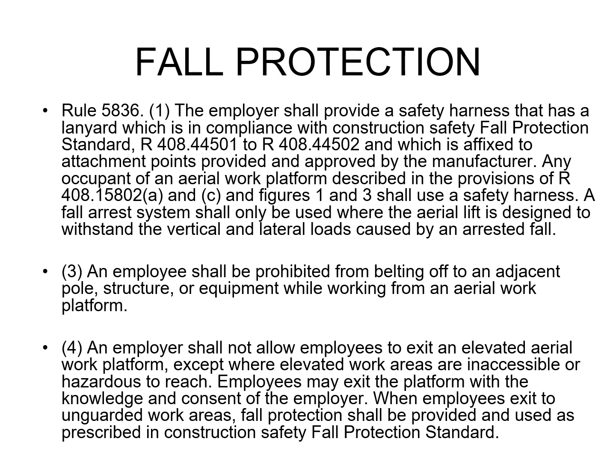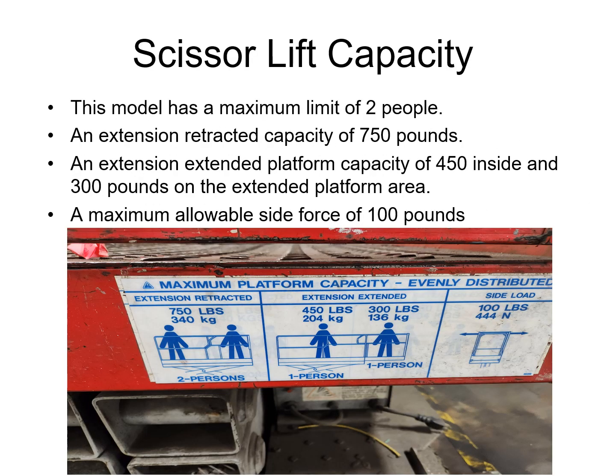Employees may exit the platform with the knowledge and consent of their employer. When an employee exits to an unguarded work area, fall protection shall be provided and used as prescribed in the fall protection standard. Scissor lift capacity. This model has a maximum limit of 2 people.